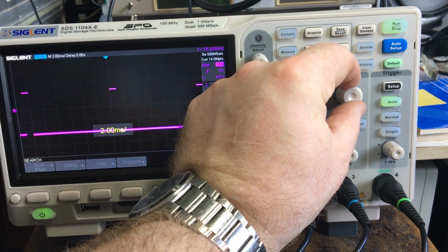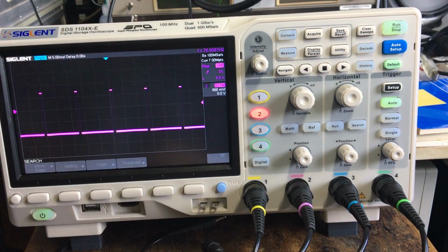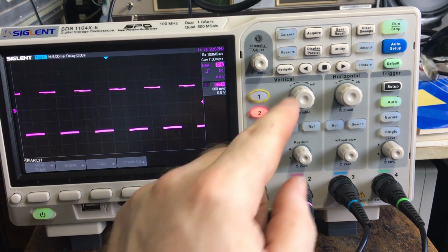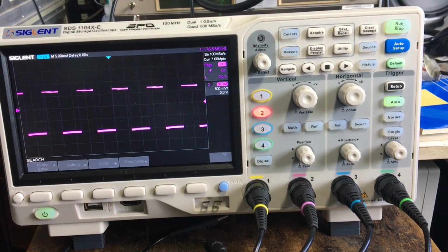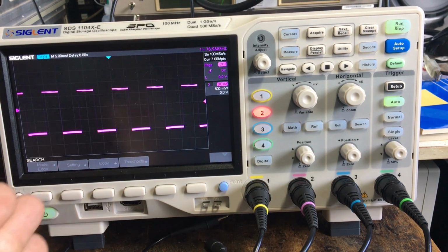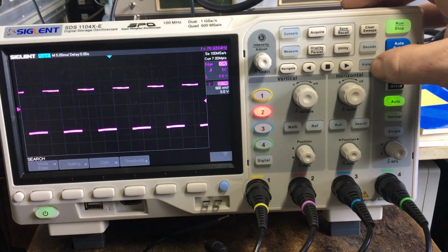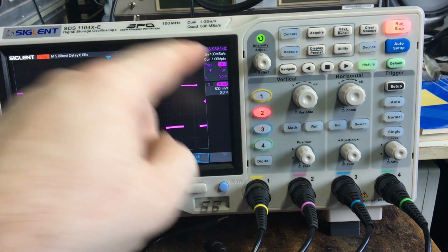Right, so I thought I'd play around with this scope a bit more, and I've got a little pulse signal coming in here. Just make it a bit broader. Now, this navigate function here is new-ish to me. It's actually fairly easy once you understand what it does. If you're using segmented memory, you can step through the segments, or it will do time stepping, or go through the history, depending on what you're doing. This has got 3 frames in here for current settings, because I've got the memory set at 7 megabytes.